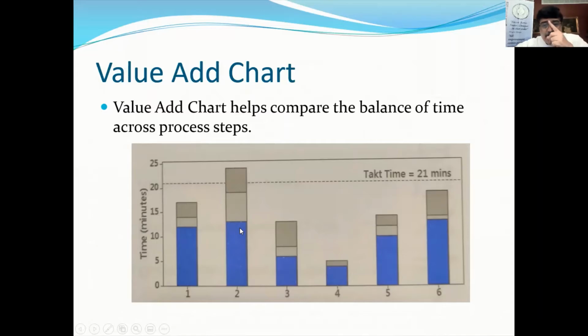So this step and this step are taking a long time. We want to analyze this time, and we compare it according to the takt time. The takt time is how much production we are expected to be completing. We have a product, and our process needs to deliver one product, let's say every half an hour. If this step is taking more than half an hour, no matter how much improvement we do to the others, it's not going to work.